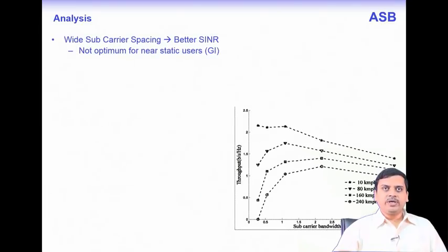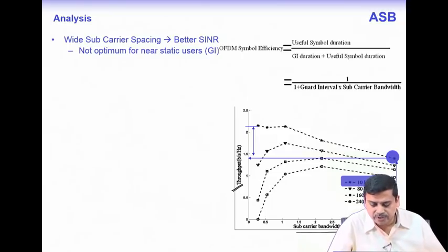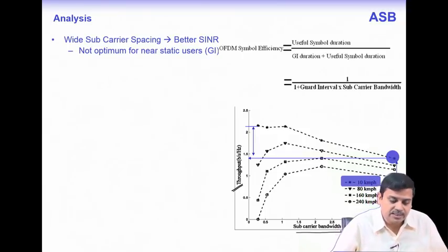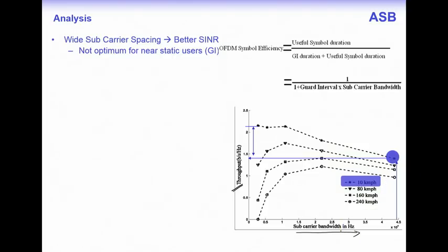So, with this we have also analyzed the throughput condition, that means when you increase the subcarrier bandwidth, what happens for different throughput conditions. What we find is that as you increase or decrease the subcarrier bandwidth, we have discussed this when talking about the frame structure: for longer OFDM symbol durations, the guard interval duration is correspondingly longer. Now, if you have a certain channel impulse response and you cannot do much with the guard interval part, that means you are restricted, then the overall system efficiency decreases, right.